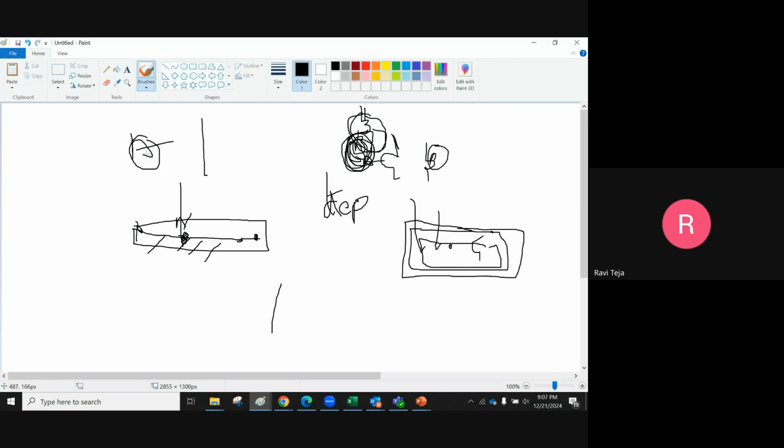For this reason, to avoid these temperature effects, we will place matched devices as close as possible. So to avoid process, you understand, voltage, you understand, and temperature, you understand, the temperature throughout these devices should be the same. If not, again the device characteristics will be changed.